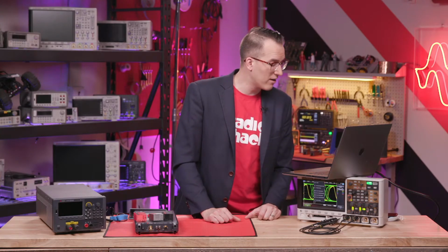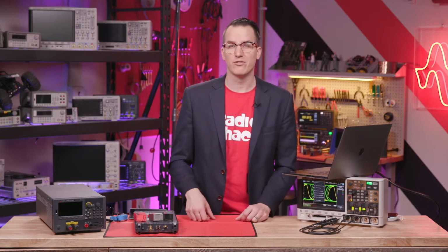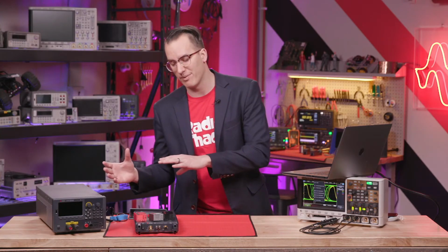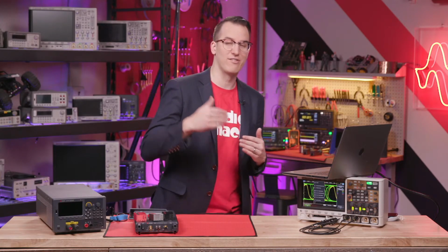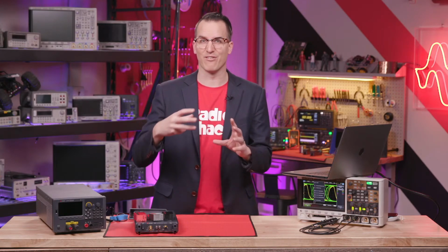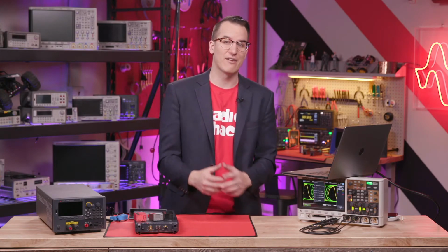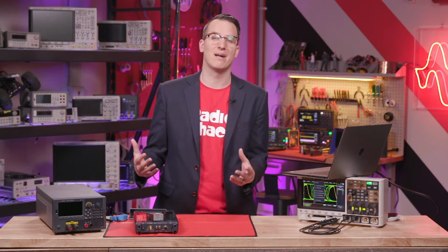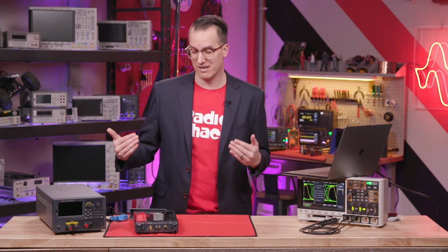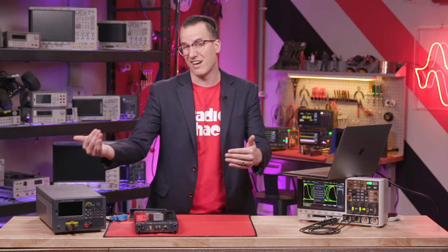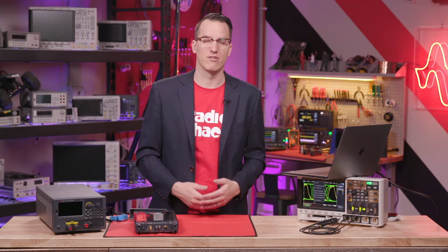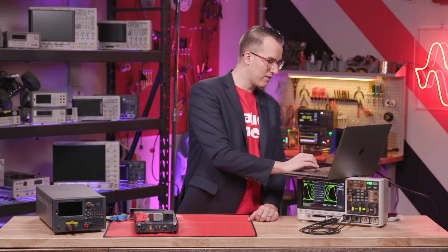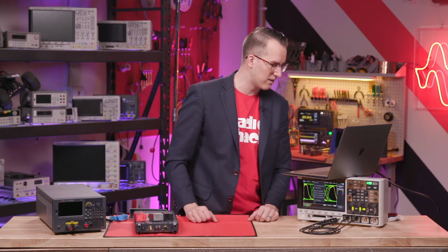Joel does say, though, that modern VNAs have a much better de-embedding function, so you can mitigate some of that. But when we talk about a calibration plane, that's what we're referring to. And then there's some fancy tricks you can do on top of that to get rid of those effects without having to calibrate. And that's really helpful if you have a complex setup. Maybe you can't go and calibrate and put your reference plane at the DUT every time. Or maybe you don't want to for some reason, for speed of testing or something like that. So there are some situations where you can de-embed those.